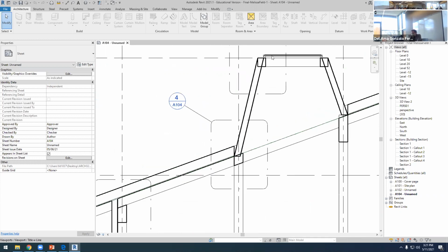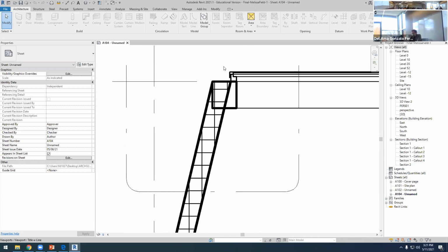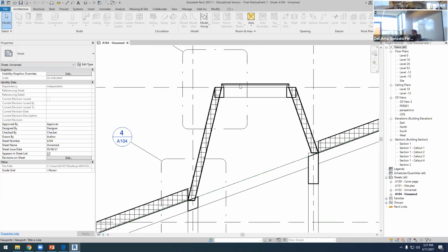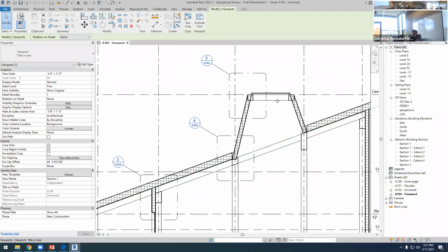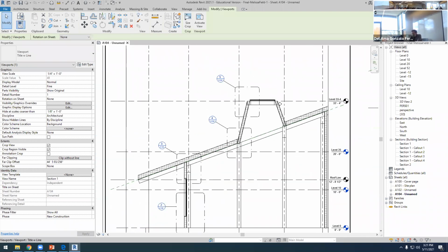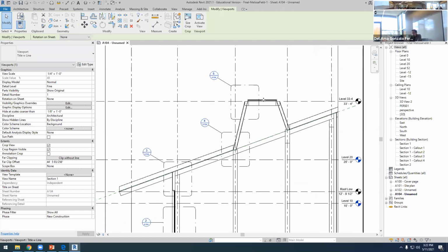Okay, but probably that skylight here, this is what I mentioned before. So I think it would be better if that skylight has a slight slope here, sloping down, not sloping this direction, but always we have to help water to get out of the building. So I think if we had the slope here, that would be better.